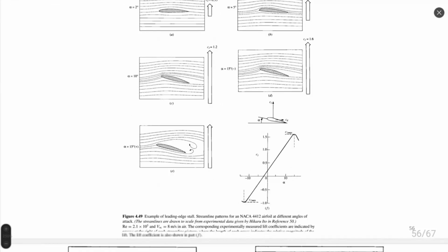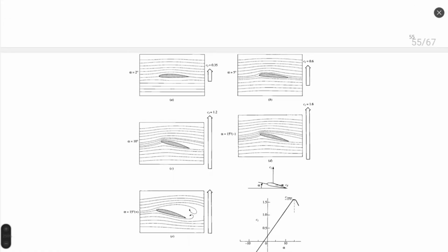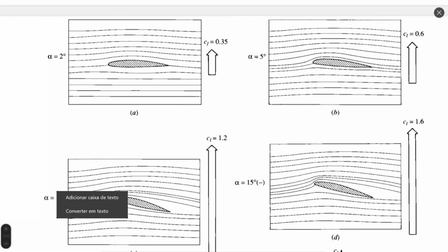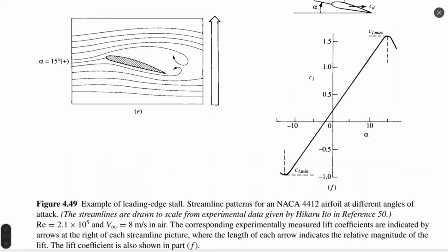In this case, real flow around an airfoil, we see three different examples. The first example is a so-called thin airfoil, whose thickness is relatively small with respect to the size of the chord. This airfoil here is a NACA 4412, a standard 4-digit airfoil with 12% thickness, quite a typical representative of a cambered thin airfoil.